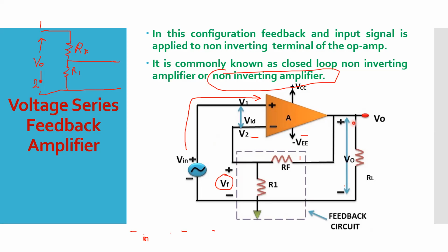So that thing will happen here also. If you use your op-amp singly, without addition of any other circuits, then it will give you the same gain, that is the open loop gain, and similar behavior with all the parameters. But now in this case, we are adding the feedback circuit. We are making it a voltage series feedback amplifier now. We are adding that feedback circuit, which means it is now a closed loop circuit, with the op-amp and that feedback circuit also there.